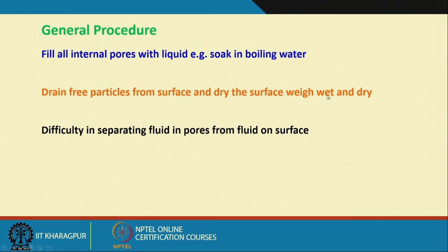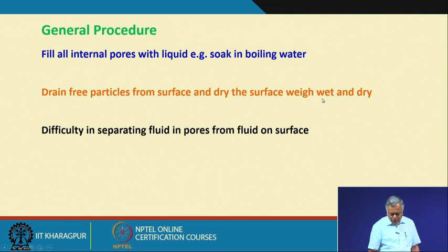Drain free particles from the surface and dry the surface. So, the basic technique we are trying to use is that you want to know how much is the pore volume, and then you subtract it from the actual weight of the sample. Then you get to know the density of that.